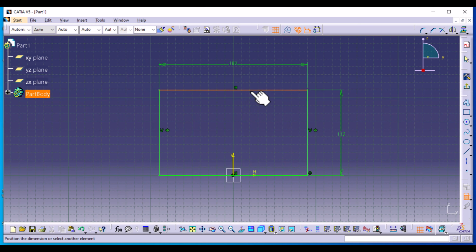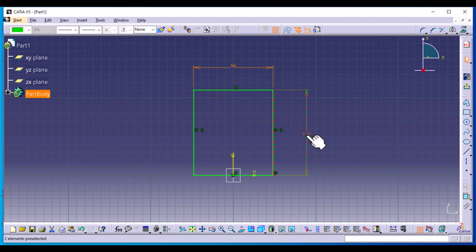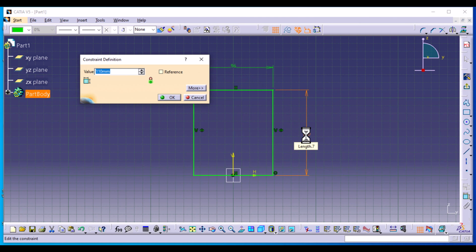Then the second one. So please note that difference, that in SolidWorks, automatically when you select a tool or a command, it remains with the cursor. But here, if you want it to remain with the cursor, you have to double click on it. Then exit. And then double click on this measurement to adjust it. Then this 96. So it doesn't pop up automatically like in SolidWorks. Double click on this and select 100.